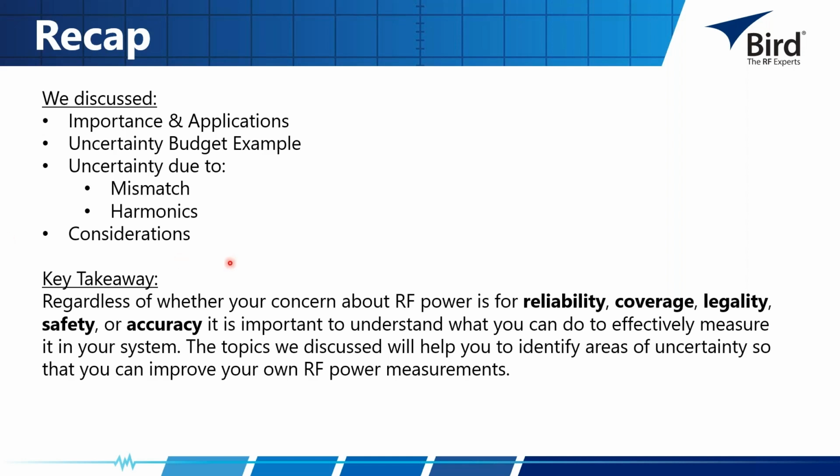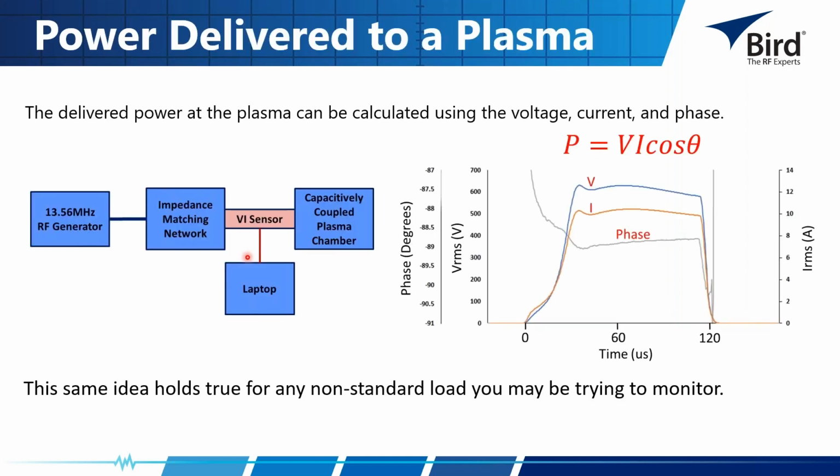Let me back up here just a moment. The device that I was measuring this item with was a BDS2. It has a through line portion of the sensor, and there's a set of cables that run from the sensor to a receiver that's doing all the high-speed processing analysis of the signal. We can reduce the uncertainty of that whole set of equipment by calibrating all of it together as a system.